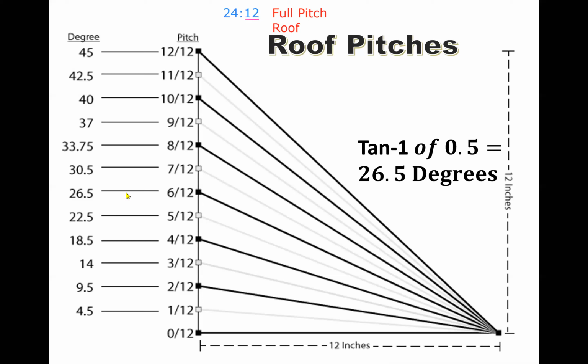Now most residential buildings are usually quarter pitch, and if not quarter pitch, most of the time they are 7 in 12, which is approximately 30 degrees. So when you are doing manual drawing and you are using your set square to draw a 30-degree line, you basically were doing a 7 in 12 pitch. It's 30.5, but most persons just work with 30 degrees.